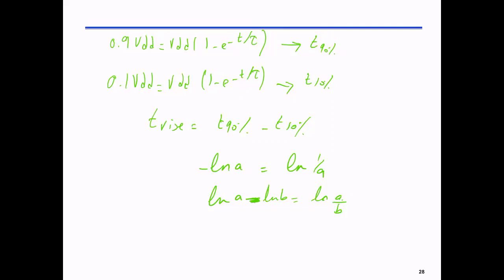Anybody has a question? Yes, Doctor, do we always refer to the rise time as going from 10 to 90, or are there some instances where we change the values? This is the default rule. If a company is interested in 20 to 80%, they will tell you to find the time it took to go from 20 to 80%. If we just say the rise time, then it is 10 to 90. Okay, thank you.